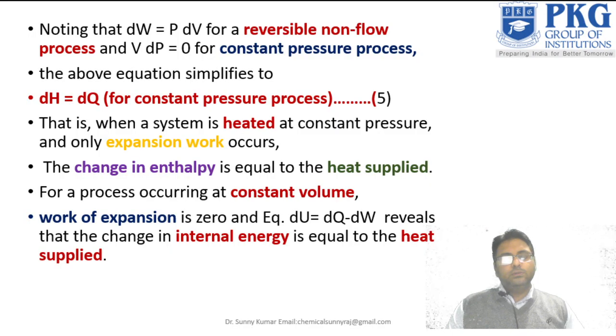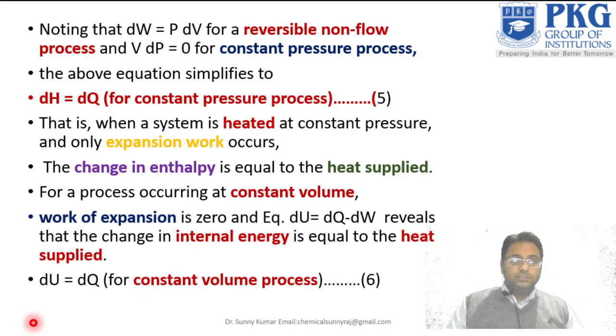So this dW equals P dV, and when there is no change in volume, dV is 0, so that term will be 0. Then the internal energy equals the heat supplied, as we have shown in this equation. So for a constant volume process, internal energy equals the heat.